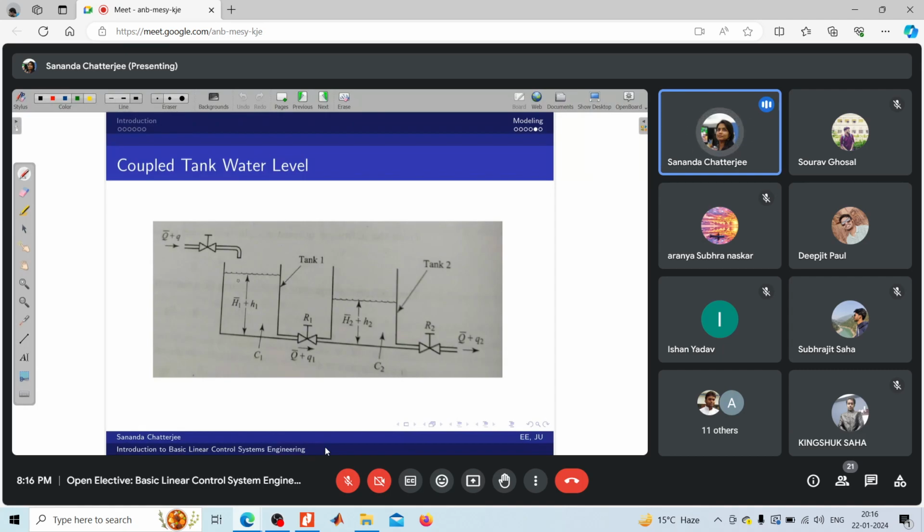So the objective is that everybody should get a constant water flow in their house. They have subscribed to that water supply system, which means there is a particular value of Q2 to be supplied to the household users. For that, the calculation has been made of what the water level height H2 of the local tanks should be.